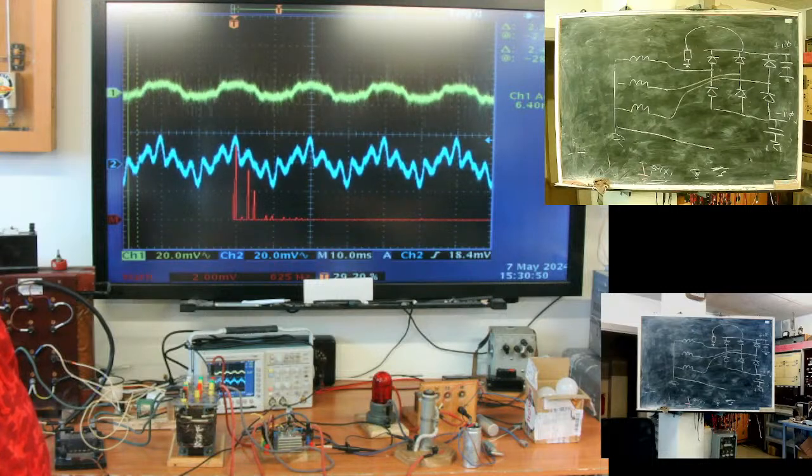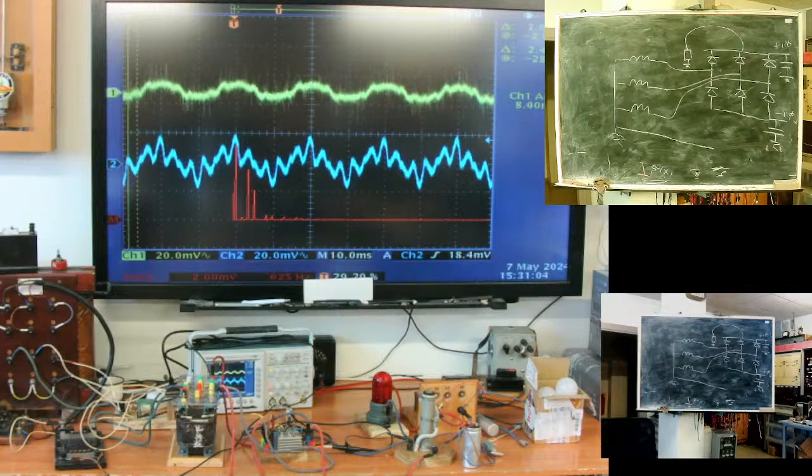For a three-phase network, we don't need a neutral line, is it? For three-phase, we can live without neutral if our load is symmetric. If there is non-symmetry, you will see a shift of center. For rectifiers, yeah, if we speak of rectifiers, they are symmetric, you don't need it. So I assume that for a symmetric network, it means the loads are balanced, right? Yeah. So what can cause the loads to be unbalanced? A lot of things.